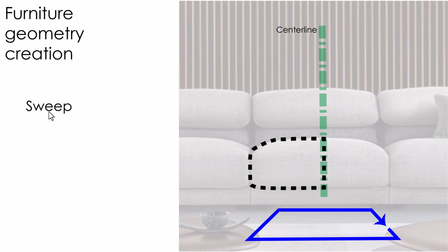Even something like a cushion. If you look at a cushion, which is notoriously hard to make look good in Revit, it actually is just a bulbous shape that sticks up. If you can draw that profile, and in this case it's a square cushion, so I could just draw the 1/4, or 1/2, I suppose, of the cushion and have it sweep around a rectangle, and like magic, you've got yourself a cushion. Again, you'd have to tweak the profile, and if you have a cushion which is different in profile on the front as it is on the sides, well, then you have a new problem on your hands.